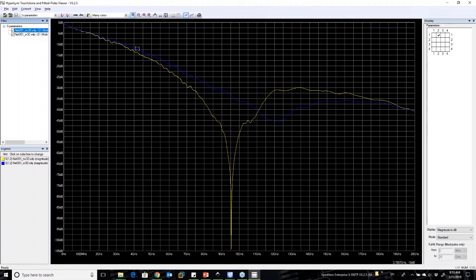So it shows that the amount of energy going through drops by quite a bit, but actually with the 3D model here in blue, you can see it's actually a little bit better. So the basic via model structure that we had didn't include the stitching vias that were helping control the impedance as it went through the power plane. So we can see that is having a positive effect. And then it's a good thing that we did have those stitching vias included in the design.